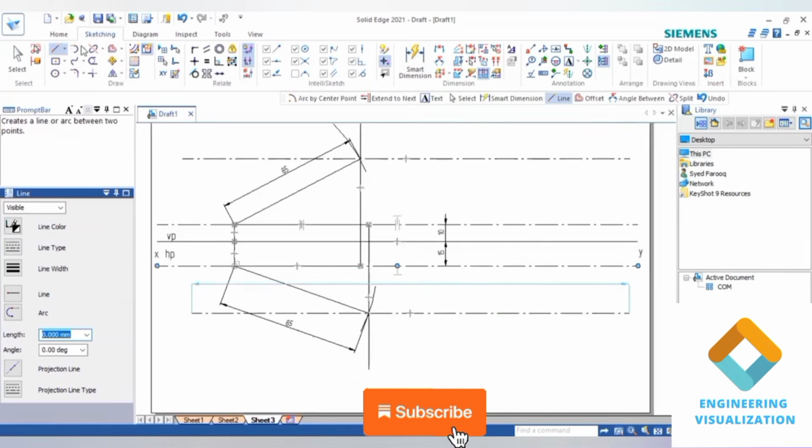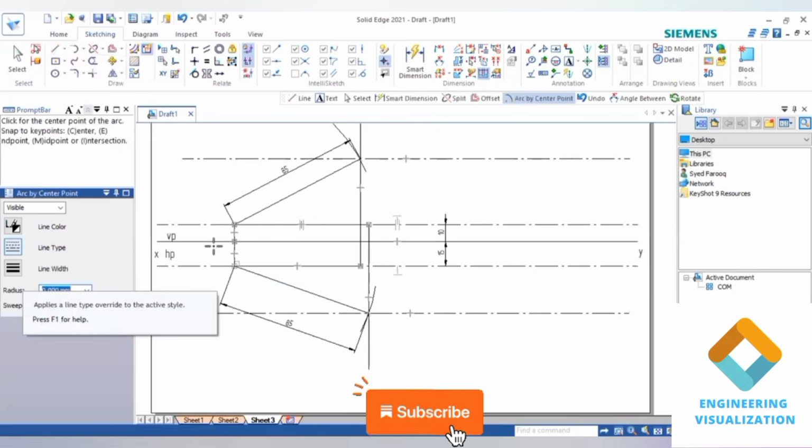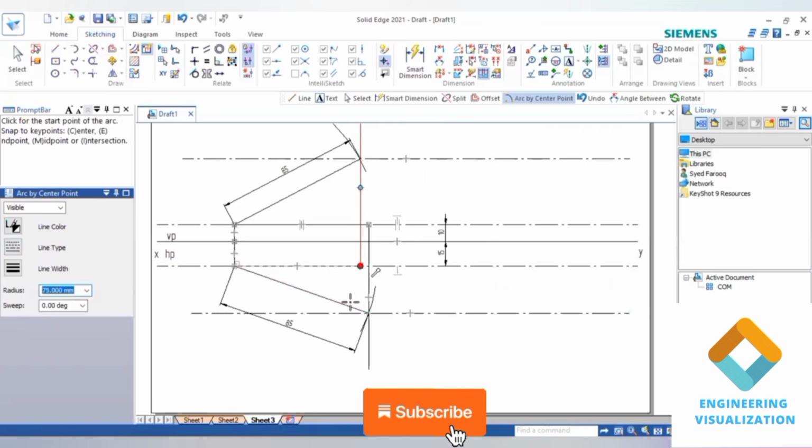Now go to arc by center. By measuring this 75 and 80 mm apparent lengths, you have to draw an arc to draw the apparent lengths. First select the 75 mm length, cut an arc. Same way for 80 mm length, cut an arc.